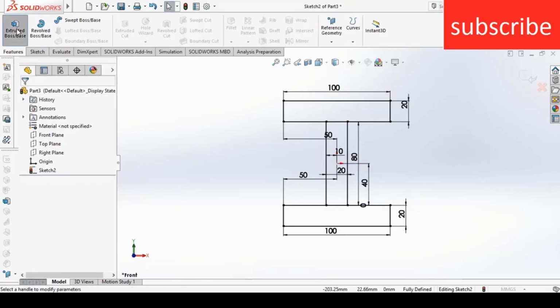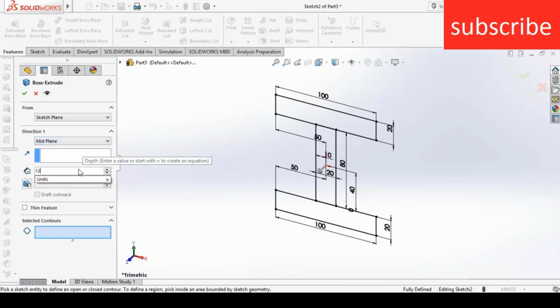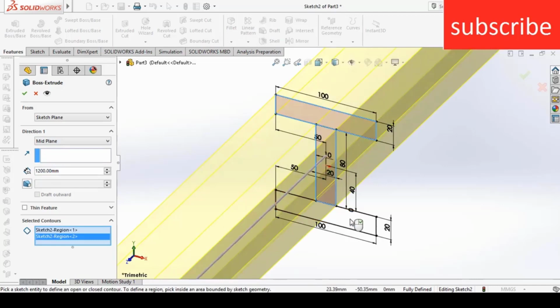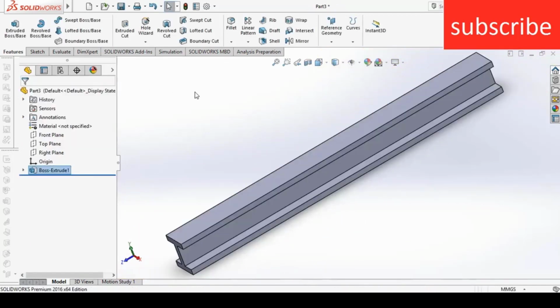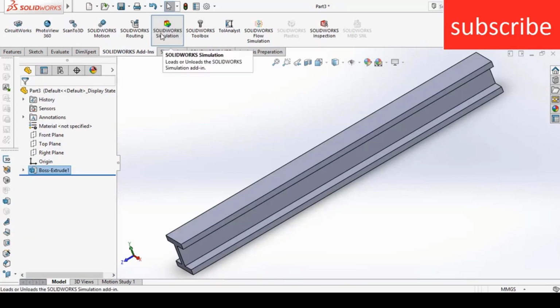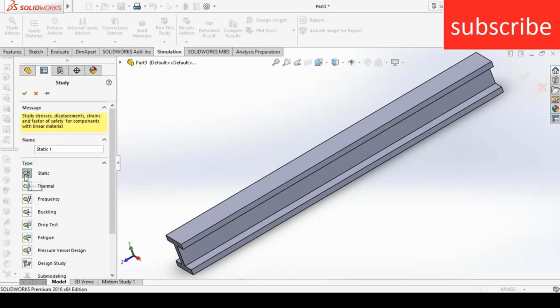Now go to features, click on extrude. Now select mid plane and then extrude up to 1200 mm. Make sure you select these things, click OK. After that, go to SolidWorks add-ins, make sure you click on SolidWorks Simulation. After that, click on simulation, go to study advisor, click new study. Make sure you click on static.